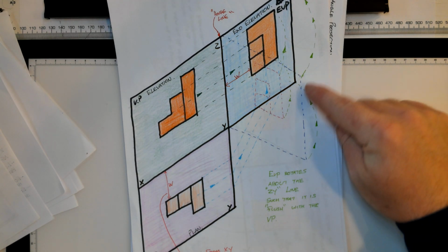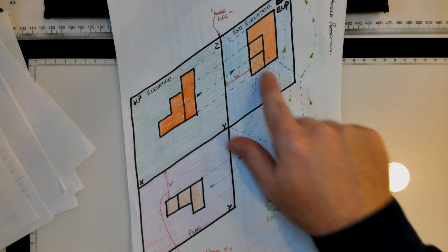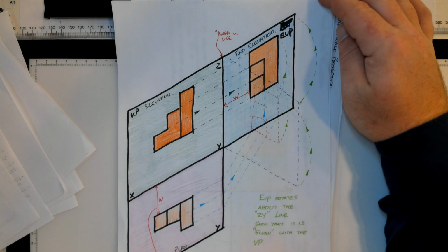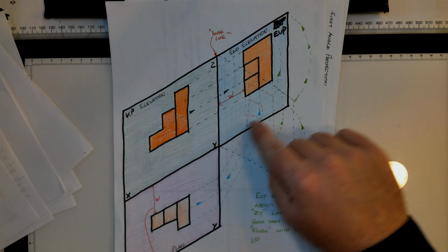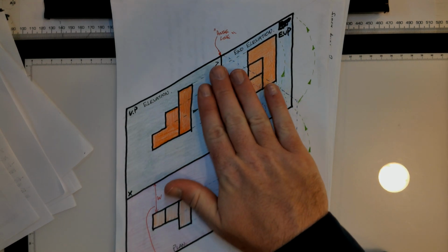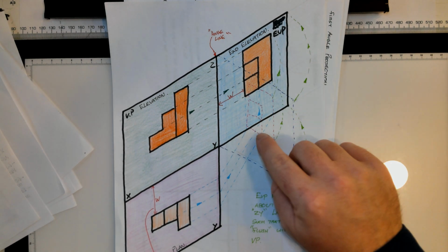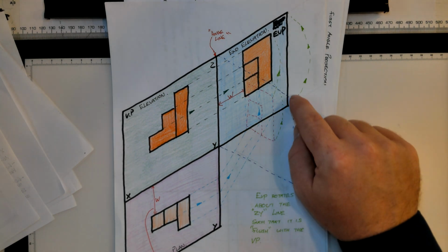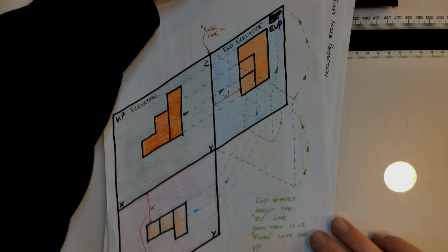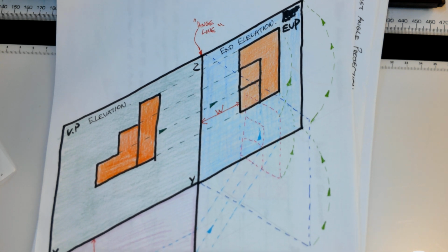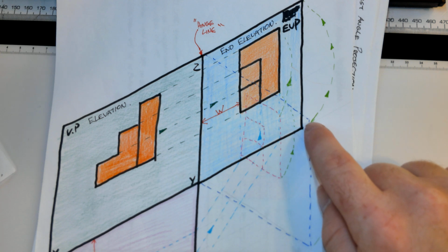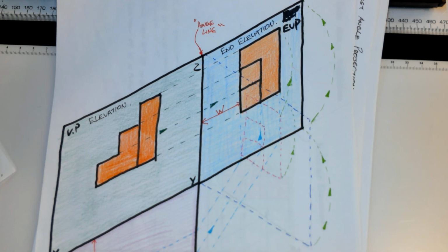If we look at this dashed blue line, we can see where the end vertical plane was, and it's now rotating or rebatting again around these green lines until it's in line with this plane here. So now it's all on one flat surface. We can see the different projections being rotated around. So I'll just zoom in a little bit. Hopefully you can see that. And let you pause it there if you need to. We have everything being rotated all the way around so that it's in line.